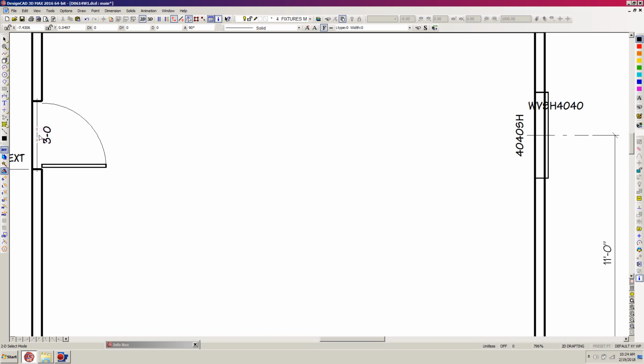So the header that I drew for this door is going to be very similar to the header for the window, with this exception. The windows extend out 2 inches past the wall line. That's just how I have my window symbols drawn. So if I Control K to the center of this window rough opening edge line, it's going to be too far out.